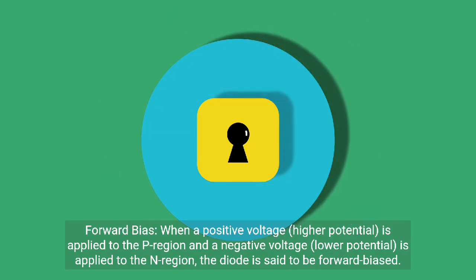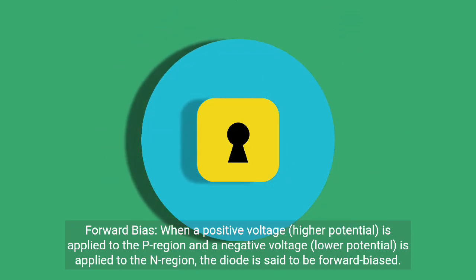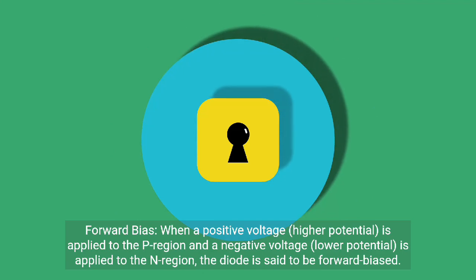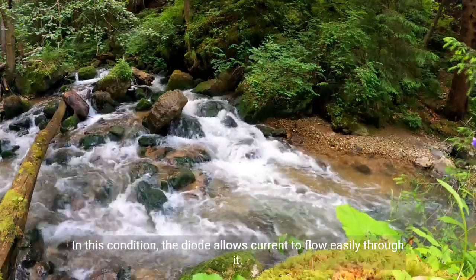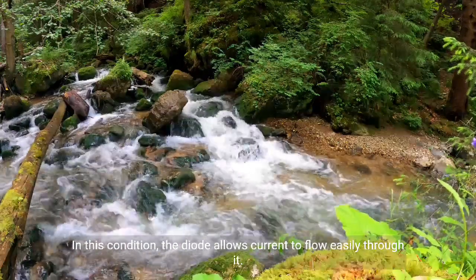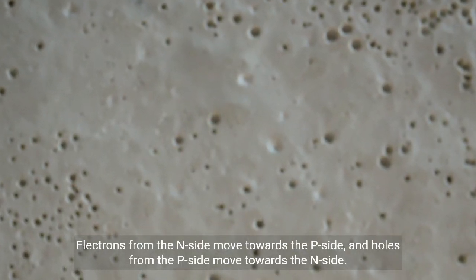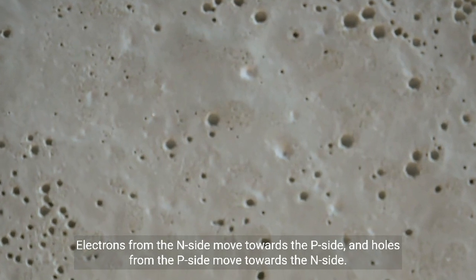Forward bias. When a positive voltage (higher potential) is applied to the p region and a negative voltage (lower potential) is applied to the n region, the diode is said to be forward biased. In this condition, the diode allows current to flow easily through it. Electrons from the n side move towards the p side, and holes from the p side move towards the n side.